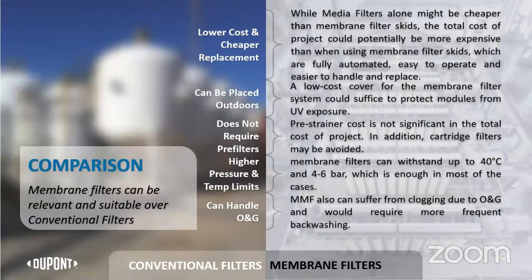On the ability to handle oil and grease, I would say that in conventional filters, it's just that the oil and grease is painful. It is hindering the process of filtration, and it's not detrimental to the membranes. Proper chemical cleaning and proper removal from the surface, be it multimedia filters or membrane type filters, reduces the headache and hindrance on filtration. So it is not a problem. If it's a problem, it's a problem for all the types of filters. It's not specifically for membrane filters.